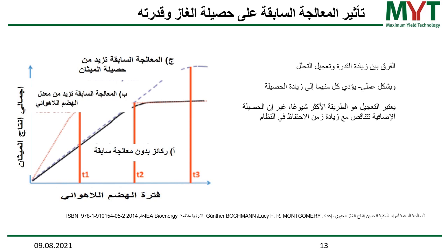So whenever you want to increase your gas production rate, make sure that your process is actually operated in a way that you have a positive impact on your gas yield. And this can only be achieved by relatively low retention times. Otherwise, the effect of your acceleration is not very pronounced, and you achieve only a little extra of gas.